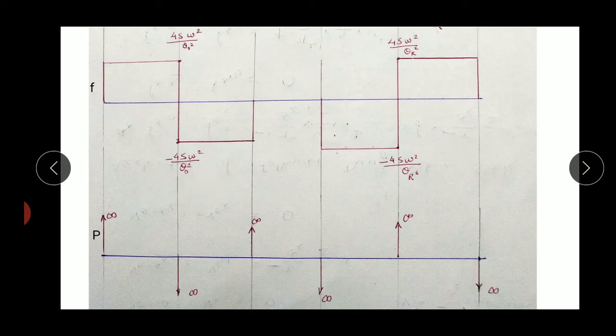Now in between the middle of the outstroke till the end of the outstroke, you can observe there is a straight horizontal line, that means retardation is constant. As retardation is constant, it doesn't have any slope. As it doesn't have any slope, that means jerk is zero in between, but at the start, in the middle and at the end we have an infinite amount of jerk.